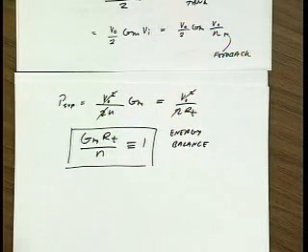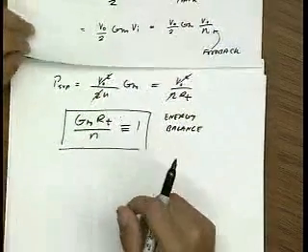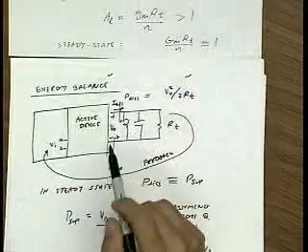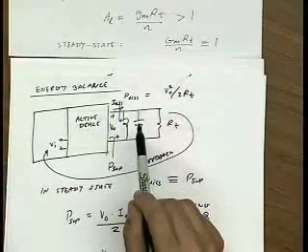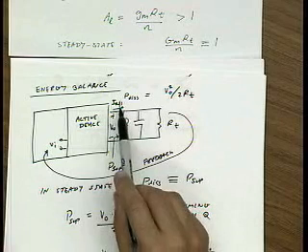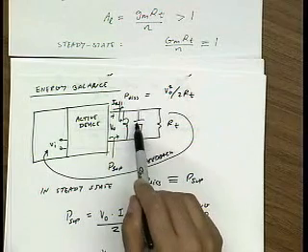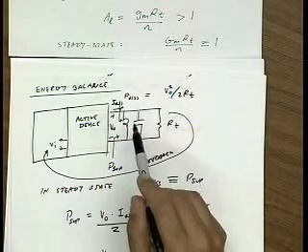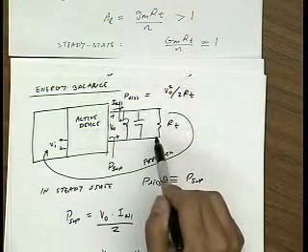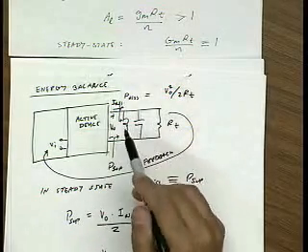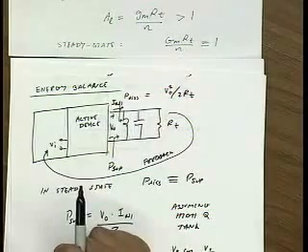Okay? Questions? Yes, David? How close is a voltage waveform close to the ideal sinusoidal? Do you have a damping on RT? Yeah, the way you can estimate how closely this is sinusoidal is you calculate how much power flows, let's say, in the second harmonic voltage. So the second harmonic voltage will be the current, basically, the impedance at second harmonic is essentially 1 over 2 omega naught C, right? And compare that to RT, you can see how much lower the impedance is at second harmonic, and that can give you a way of calculating.